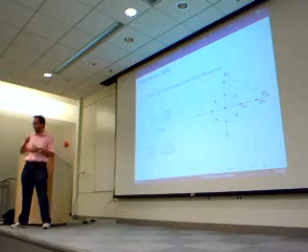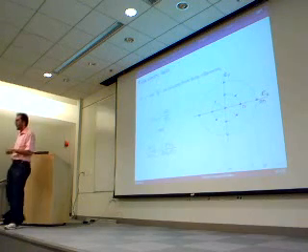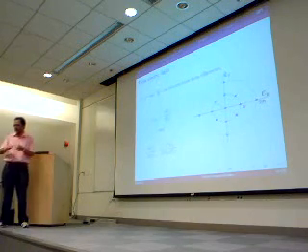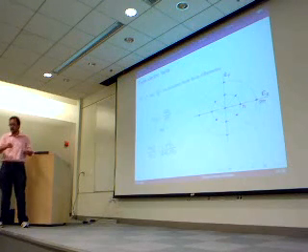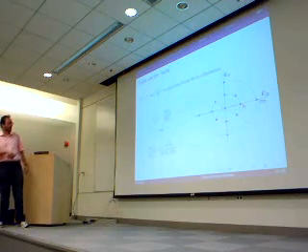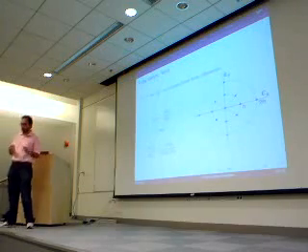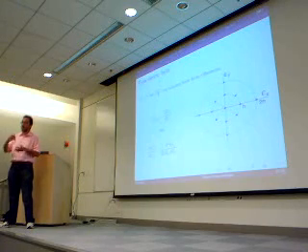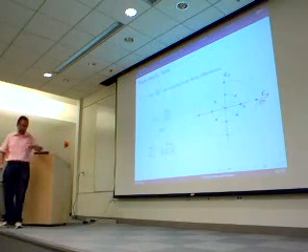We can select a value and a direction for the electric field, and we can relax the system with the electric field, either letting the atomic coordinates relax or keeping them fixed. Then, when the electronic structure has been relaxed with that value of electric field, we can obtain the polarization for that value of the electric field, which is what we want to calculate.